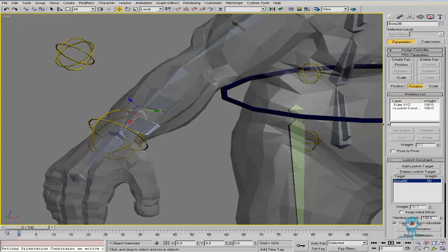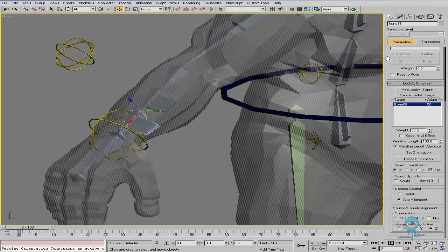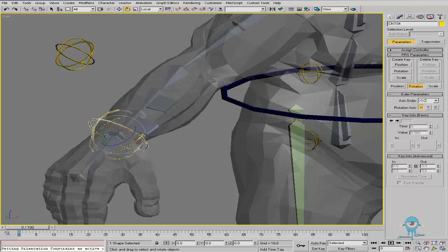We're going to fool this bone into believing that the rotation axis is different by playing with the source up node alignment. What the source node up node alignment will do is actually change the orientation of the bones to begin with. Aligned to up node axis, you can switch as well to flip it back. And if we play around with that, we should be able to get it to a point where up and down it no longer flips at 90. It flips at 180.